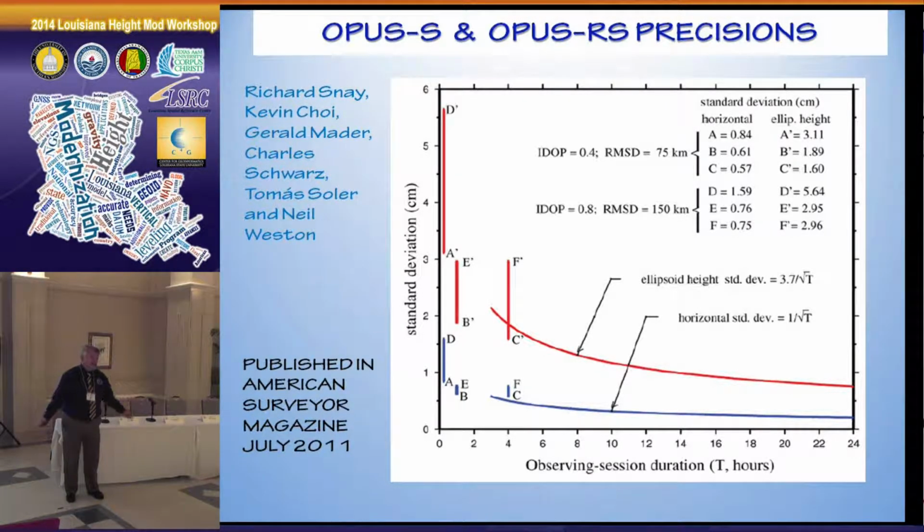It depends. So one thing you'll hear said this afternoon is redundancy. The only way to have confidence with a GNSS derived point is to have redundancy. Okay, and usually it'd be better if you use different satellites to do it. I'm not talking about GLONASS and GPS, I'm talking about different times of the day when you have different satellites. So we'll talk about that.